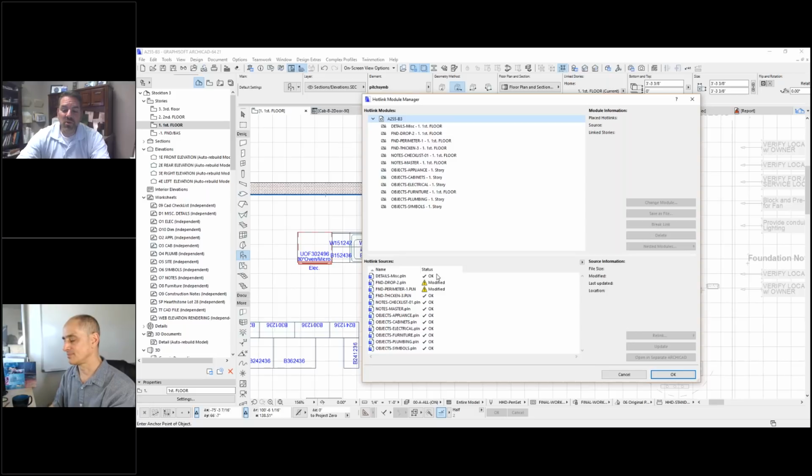I'll tell you this story on the rafter plan. I used to edit every rafter in the roof wizard, and I would have to explode the library and then make a new IFC in order for the rafter wizard to work, taking into account my edits that I did in order to have text show up for the rafter lengths.